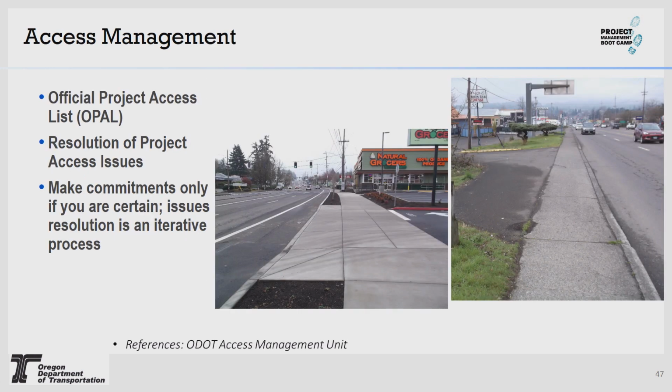One thing on striping, we would like to make sure, when we are removing the stripes, the goal is to repave those stripe-removed sections, because the ghost lines, if we don't repave afterward, just become operational and safety issues down the road.